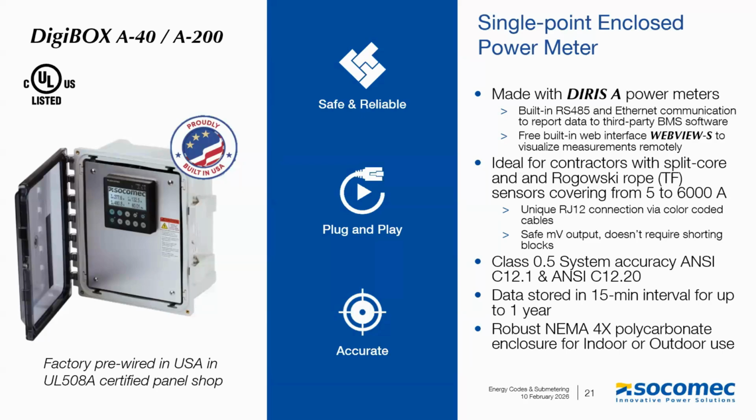They're ideal for electrical contractors. Like I said, they're enclosed, they're factory pre-wired in a UL 508A panel shop. So you're getting a certified, safe solution. It includes the fuse protection inside. It's Socomec technology, so it's got a class 0.5 system accuracy, including RCTs. So it's not just meter accuracy, it's meter plus CT accuracy. It exceeds revenue grade standards. So that's the Digibox A for single point metering. It has built-in communication, of course, so Modbus and BACnet are built in.